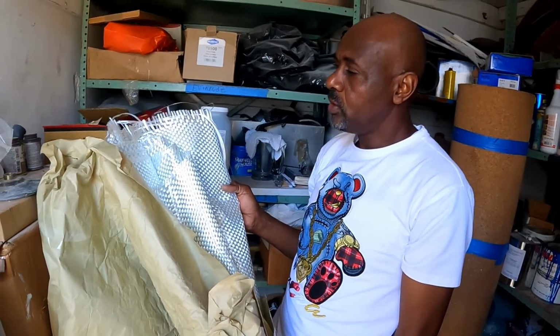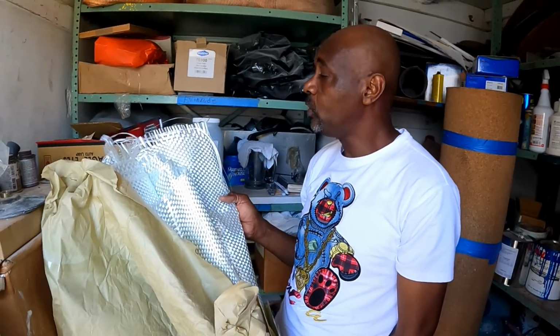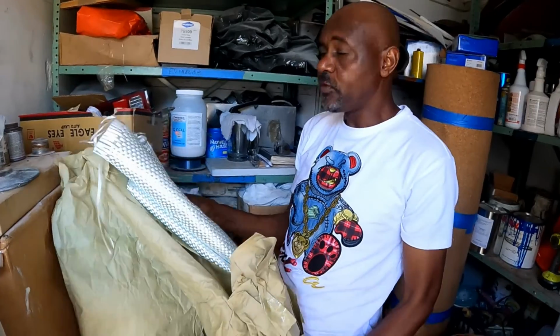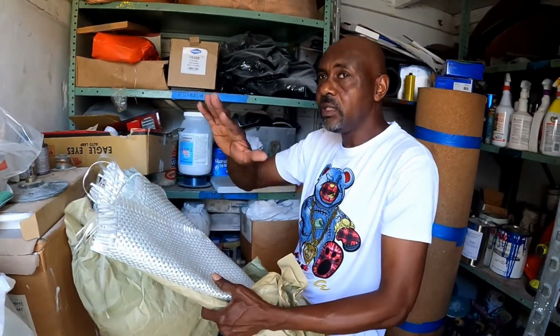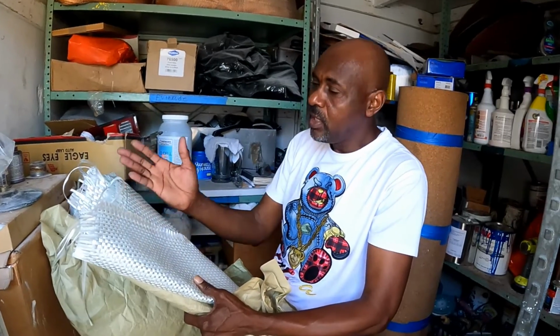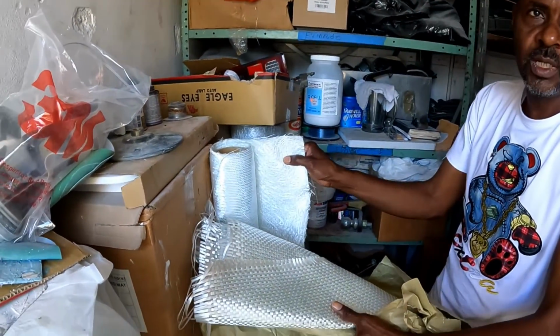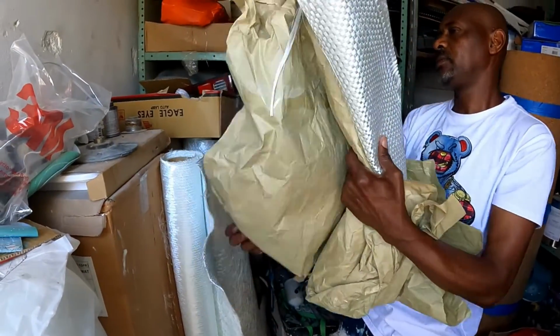Woven roving, yes. This is what you want to use in areas that are not going to be finished, because if you're going to finish, it's going to take more to finish. So you want a smoother layer after. You need a lot of resin with this. But you can use it to build or rebuild anything. But in order to have it smooth out, you go with this after and then finish it up. And then finish with that. Okay, this is the process. Yes, this is the process.